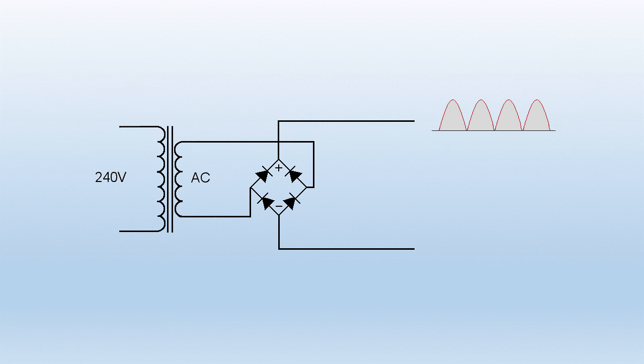And the result, as you see there, in both half cycles, we get current flowing through the load, and therefore we've got much more power available with what is known as full wave rectification. And again, if we wanted to, we can use smoothing capacitors, and they'll be more effective in this case because they've been recharged twice as often.